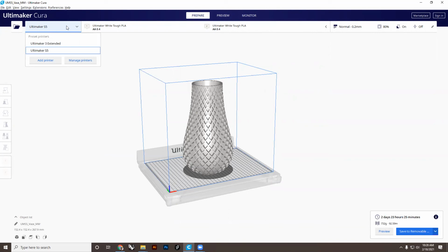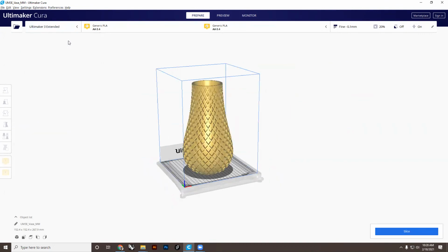This is the specific material I have to print on. And then it'll just be a series of coordinates that's telling the printer, go to this location, go to this location, go to this location, and all the way throughout the printer. Once you do that, it's already been generated. There's not a way to go back in and really alter that information. Whereas if you just save the Cura file, even if you've made a mistake on the setup, or you have different materials, or you have generic materials set up, the Fab Lab monitors can go through, adjust that for our materials and adjust that for our settings, and they can go ahead and slice it, and then they can send that to the printer.